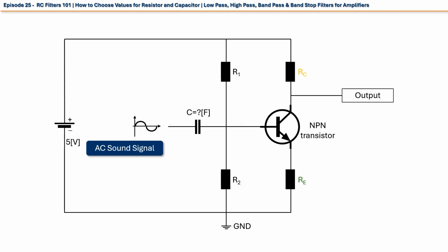From the AC signal's point of view, the 5 volt battery doesn't exist in the circuit. The AC signal sees the DC power source as a very low impedance resistor, whose value can be safely disregarded. So, in short, for the AC signal, the battery in the circuit doesn't exist, and represents a closed circuit. So, from a strictly AC point of view, we can erase the battery entirely.